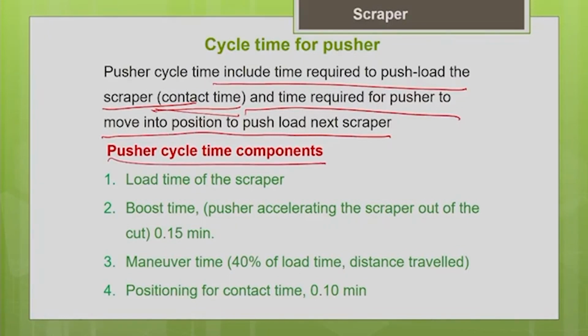Okay, let us see in detail what the components are. One is the loading time of the scraper, and the other one is the boost time. The pusher will accelerate the scraper out of the cut, so that is called the boost time. Pusher accelerating the scraper out of the cut, say approximately 0.15 minute can be taken as the boost time. Apart from that, you have the maneuver time.